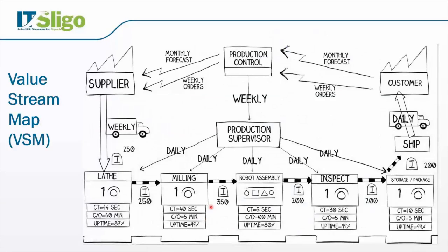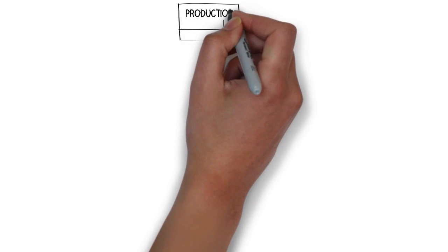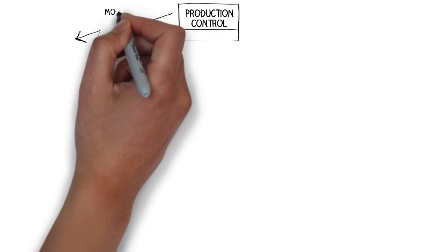So the finished value stream map is this. We're going to go through this in a lot more detail. We're using symbols for different process steps, for different material flow, different information flow, where the inventory and where the stock is. So we're going to map this out by hand and then come back and discuss it. So it's recommended when you're doing a value stream map that you get a pen and paper and you draw the value stream. And in this case, we're mapping material and information flows.